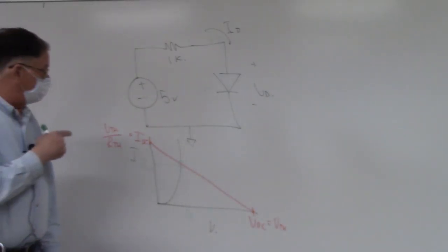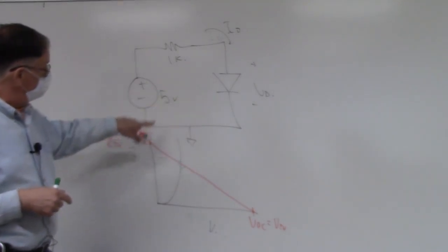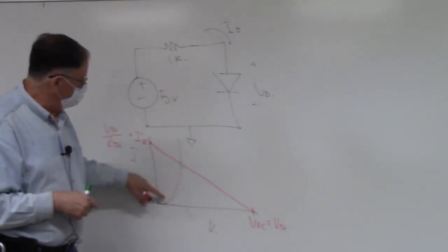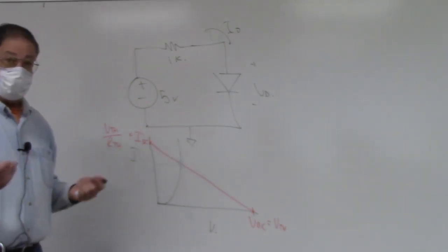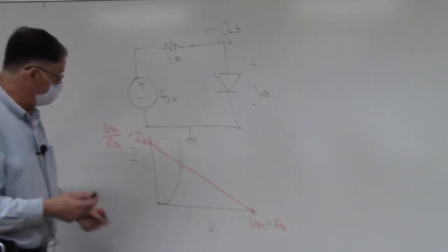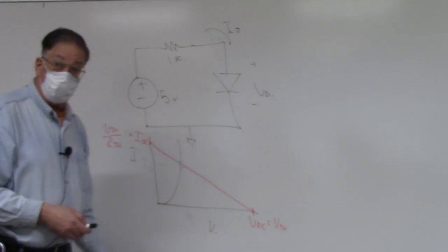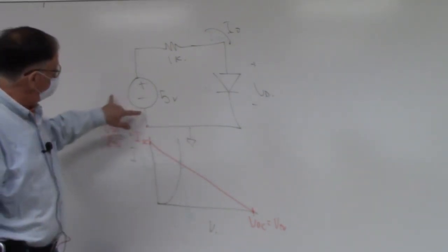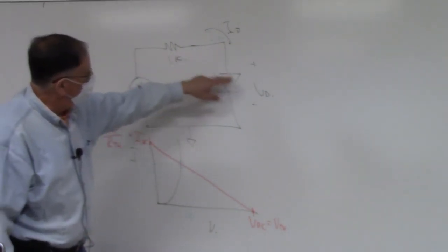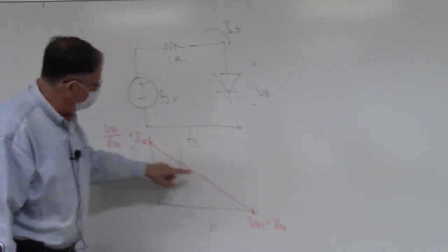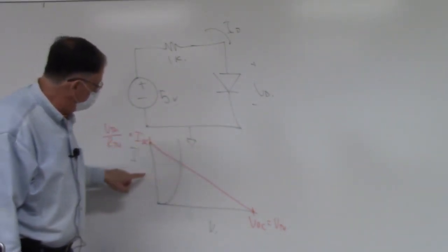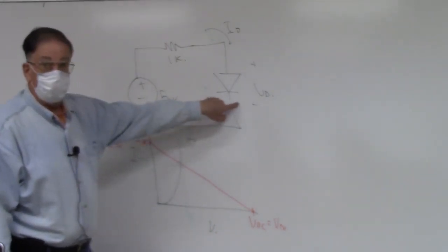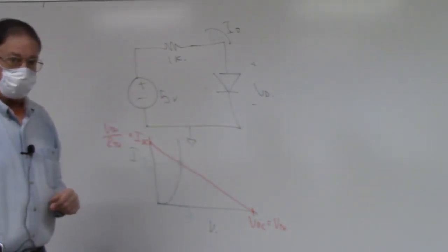And so remember, the point of this is that we can use graphical means to predict the operating point, the voltage and current, even of a nonlinear device like a diode. So that's what you have to do for part 2. Go back to your setup, set your supply for 5, measure ID and VD. And then on graphs, you can do this after you leave lab. Graph these two curves, see where they intersect, ID, VD, compare them, give me a % error. That's part 2.